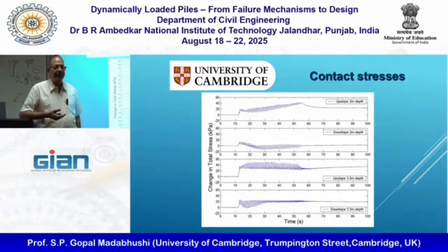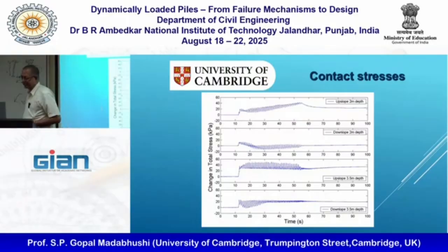Actually, they work better in this kind of earthquake problem because all the arching effects get destroyed when you start shaking the soil. So it's not as bad as in some of the static earth pressures you would measure.